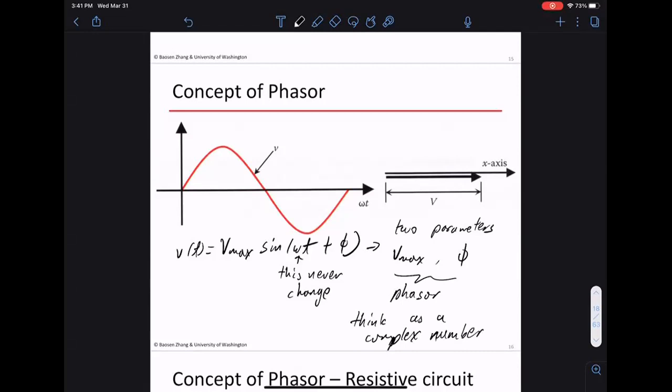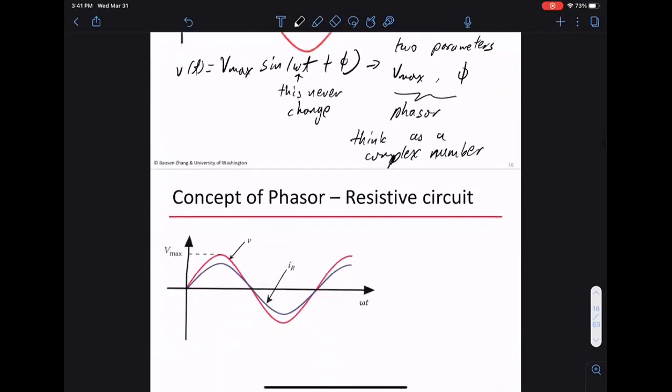Okay, so much easier to think of this complex number, just for economy of thought. Right? We can do this. So the phasor is simple, easy to work with because now I don't need to draw the sine and cosine waves anymore. Basically, the goal is not to draw this kind of picture anymore. It's to have an algebraic way of doing calculations. And the phasor is something that essentially does this for us automatically, right?